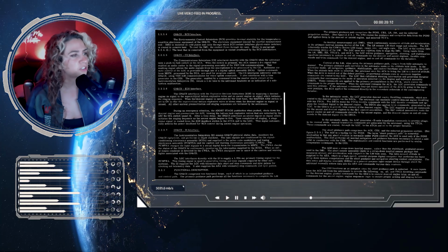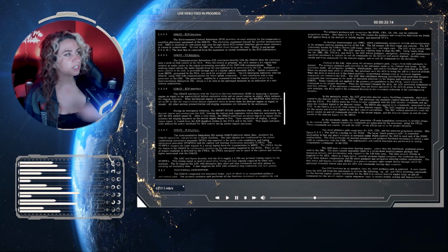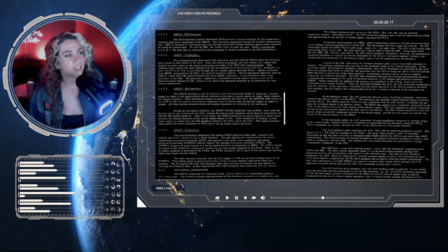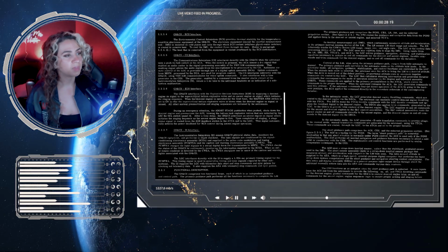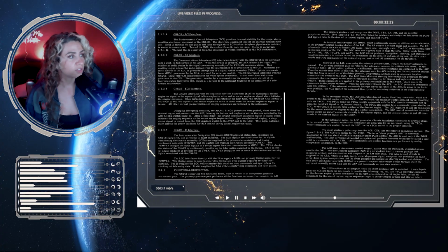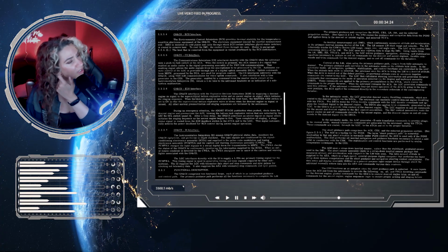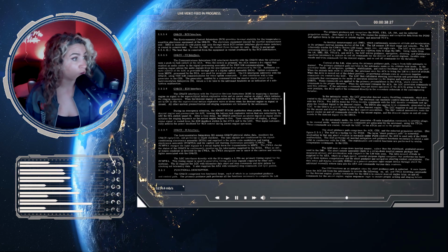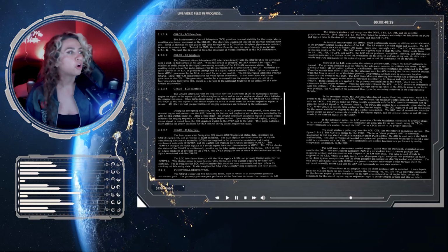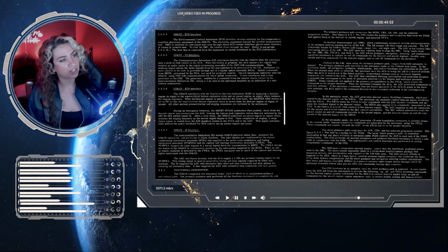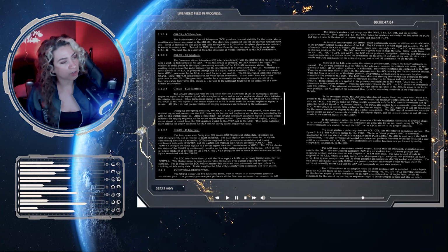And an ascent engine on signal, which initiates the staging sequence. When the descent engine is operated for the first time, the master arm switch is set to on, so the supercritical helium explosive valve is blown when the descent engine on signal is issued. All other normal pressurization and staging sequences are initialized by the astronauts.